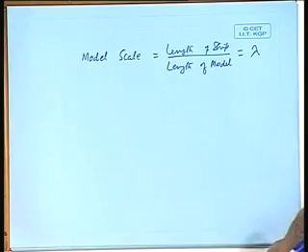So, if I have a 100-meter ship and I want to test a model of that, I may decide to go for a 2-meter model length, then the scale will be 50. Then every model dimension is reduced by the same ratio. So, what happens to the model displacement? How much should it be?